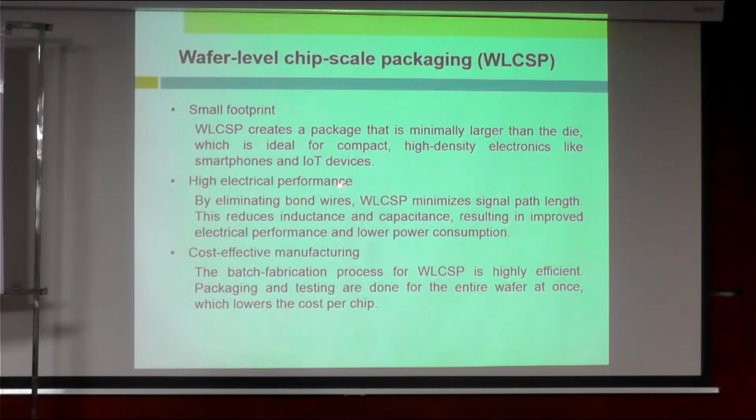And high electrical performance because it eliminates wire bonding, and because you have a through silicon via as well, it minimizes signal path length. This reduces inductance and capacitance, and it is cost-effective manufacturing because it's a batch production, batch fabrication process for the chip itself.